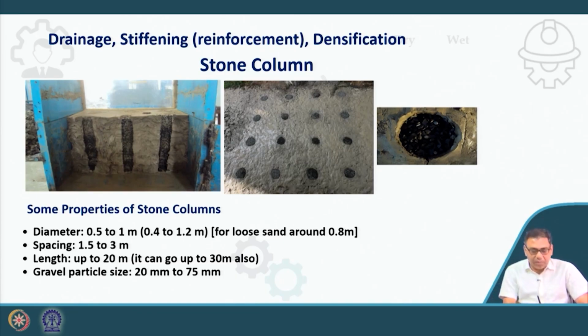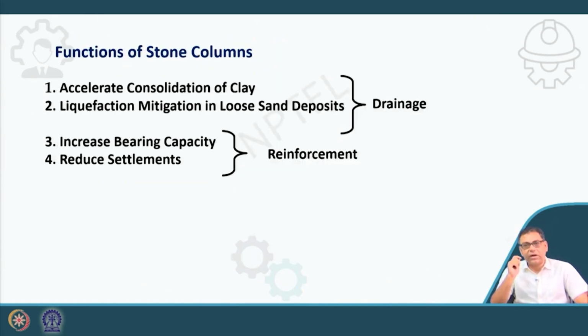Now, as I mentioned, these are the properties. What are the different functions? As I mentioned, it has mainly two functions: drainage and reinforcement. If it is used for drainage purpose, then it can accelerate the consolidation of clay and reduce the consolidation time. Another one is liquefaction mitigation in loose sand deposit. Here it acts as a drainage path.